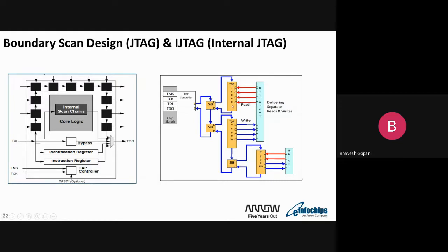Let's say this is a 130-bit TDR, so I need to program a 130-bit shift register, and those registers provide input to this PLL IP. The PLL IP will generate some outputs, and the output again goes to some TDR, and we can read it back to the TDO. So this kind of structure is placed in SOCs.